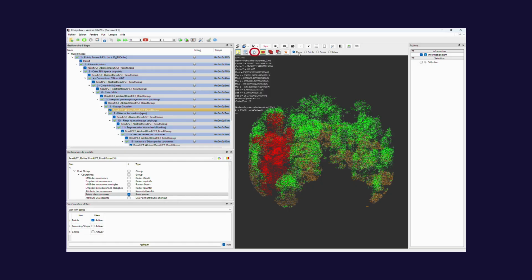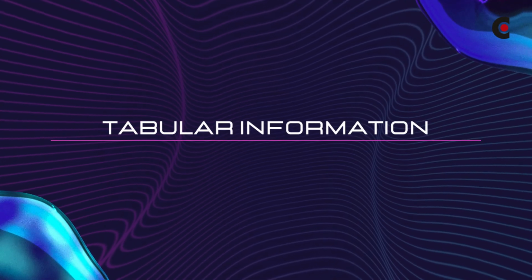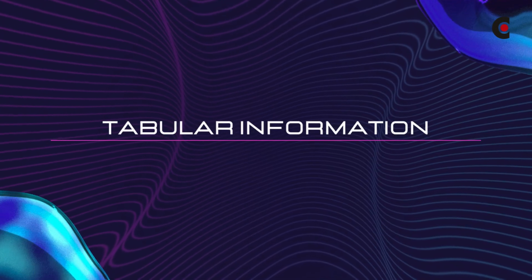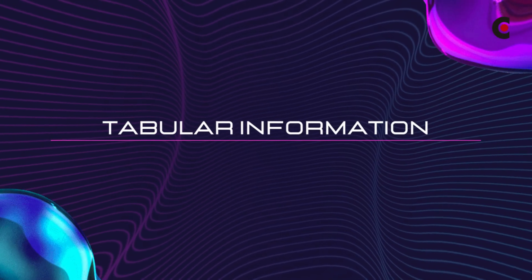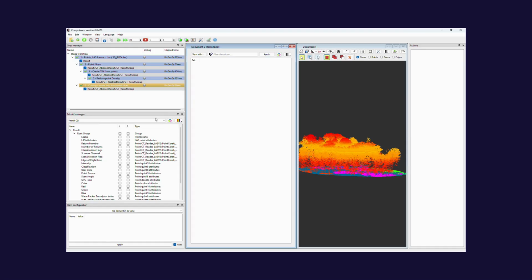You can also view object information in a table format, organized into rows and columns. This view provides a structured way to visualize all the data associated with a specific type of item. To do this, click on the icon to add a table view. You will then be able to see a list of item information by checking their boxes in the Model Manager, in the column corresponding to the table view. You can enlarge the table by clicking the following Expand button.